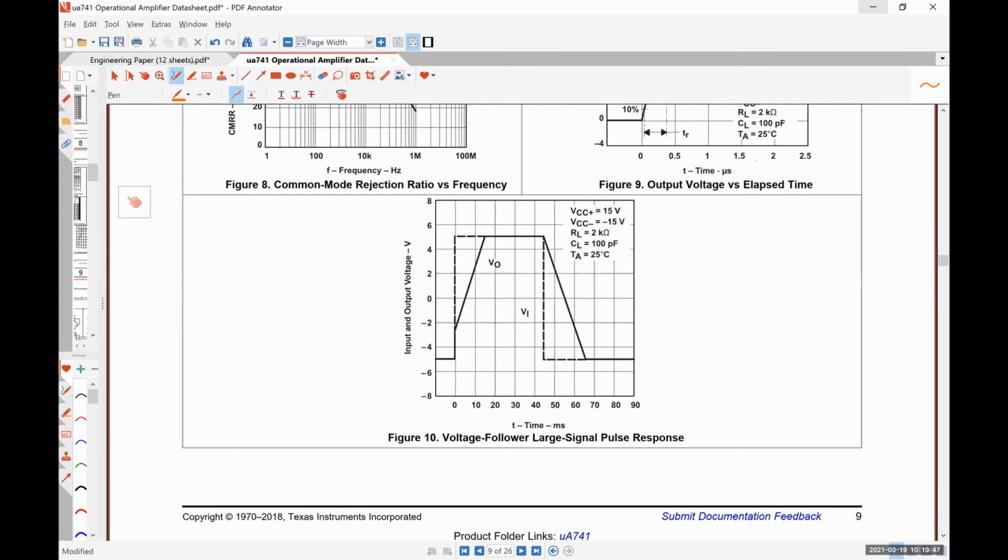But they do it in a very, very specific way. Slew rate is measured by determining the amount of time it takes the signal to go from 10% of its final value to 90% of its final value. In this case, it's at -5, so a change from -4 to +4 would be that overall 80% change in the signal.